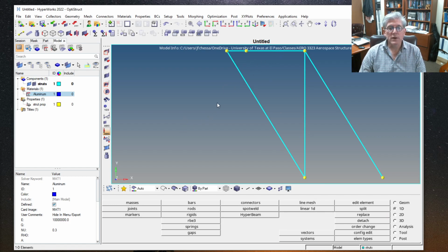They're the same color, but that's because they're rigid elements. If you want to, let's see if we can do it. We can have them colored by, I think, configuration. Yeah, so if I change the coloring of elements from by part to by config, you'll see that they look different because they have different configurations. This rose color is for C-Rod, and the purplish is for rigids, okay? So that's what it is. All right, probably can save it again.